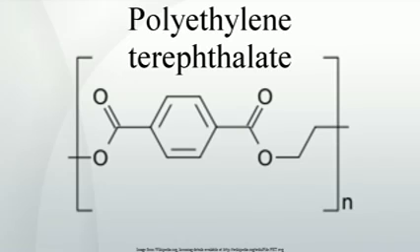Physical properties. PET in its natural state is a colorless, semi-crystalline resin. Based on how it is processed, PET can be semi-rigid to rigid, and it is very lightweight. It makes a good gas and fair moisture barrier, as well as a good barrier to alcohol, requires additional barrier treatment, and solvents. It is strong and impact resistant.